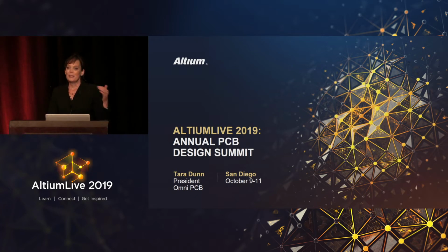Proceeded to eliminate all material in that bend area. We oriented the part in the grain direction of the material to make it a little bit more flexible, and then we added polyimide stiffeners on each side of that bend area, so we were certain it was only bending in the area that it was designed to bend in. Shipped the parts, phone call, again, Tara, this isn't working, and we were all like, what is going on?